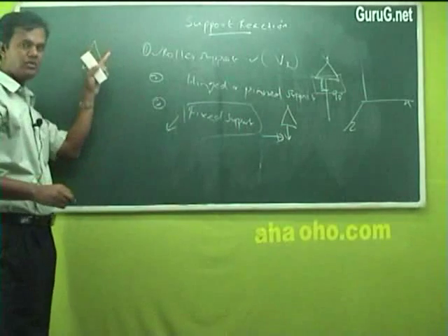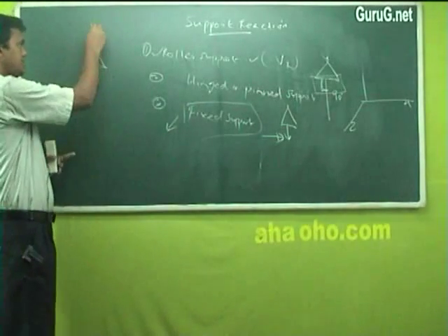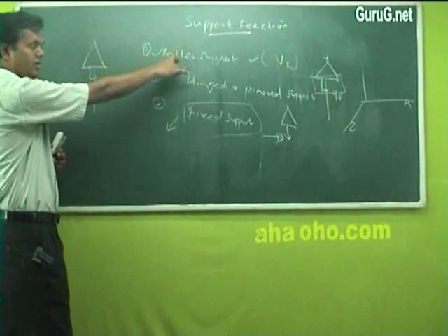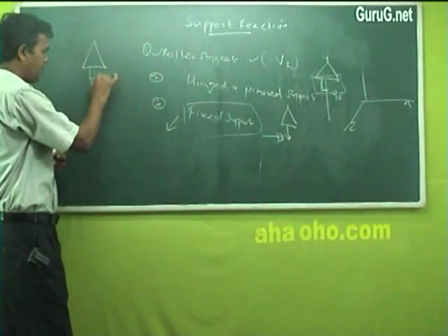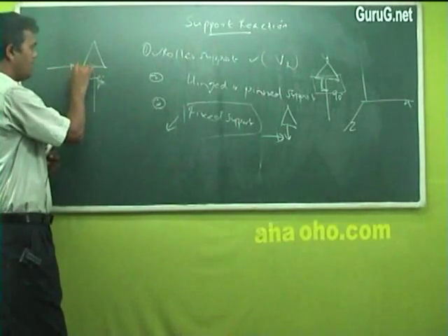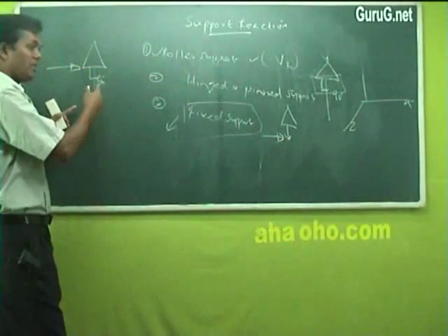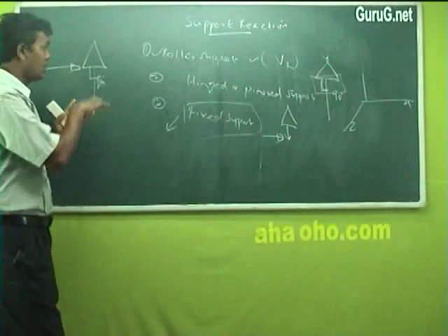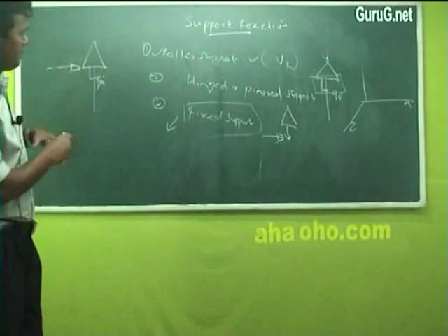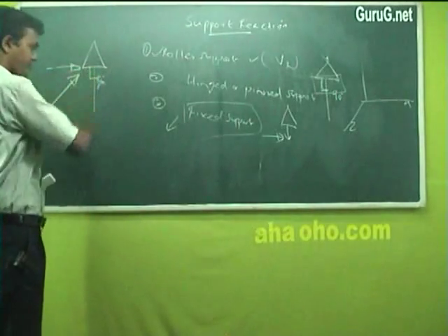That I can say in terms of this. Again, I'm just showing you the structure of a body, right? So this will have some loads. I can say a vertical support will be given by your roller support, 90 degrees apart, normal to it. And horizontal by the hinge support. What about the twisting movement is a question, because the loads will not always be either vertical or horizontal. It may be in an inclined direction also.